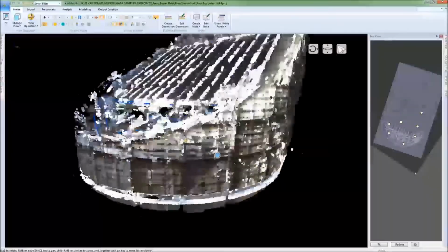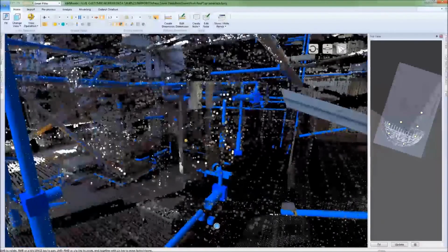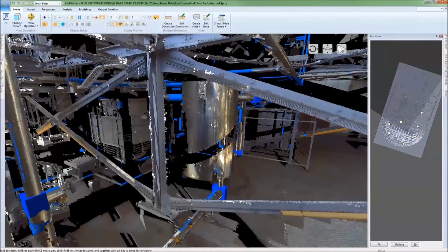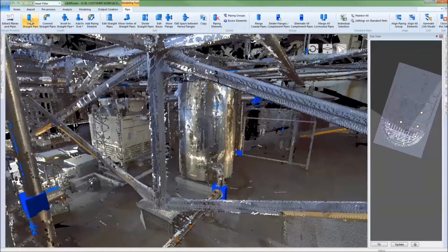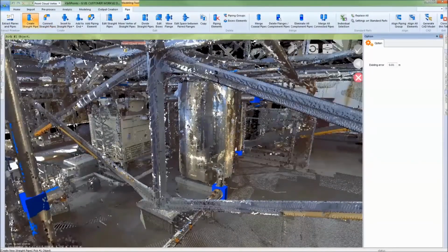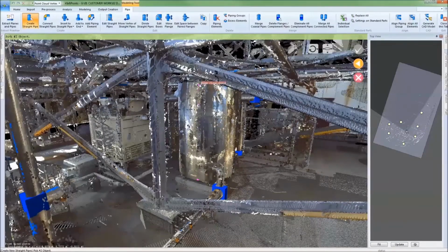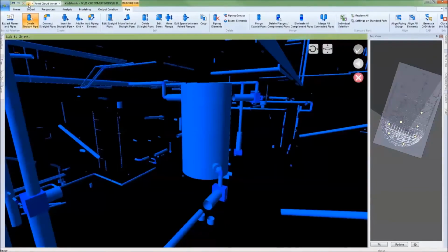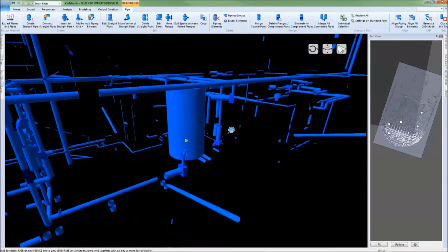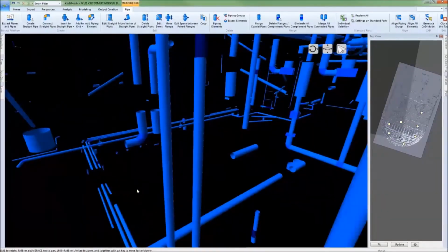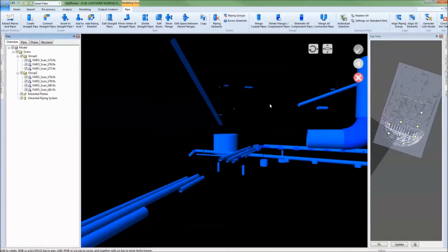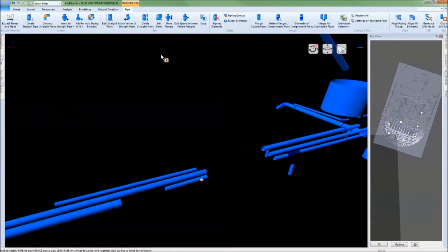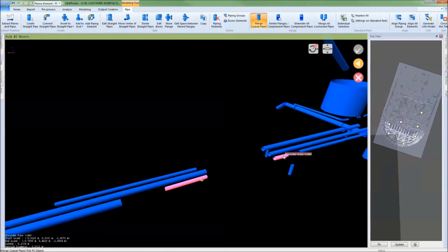Thank you, Danielle. What is great about the pipe modeling tool within InfiPoints is its versatility without the need to return to a CAD system for initial modeling. For example, InfiPoints allows for the creation of pipes based on the point cloud that may not have been automatically recognized just by selecting 2 points. From there, pipes that were automatically extracted in independent segments can simply be merged together by selecting 2 or more cylinders that are of similar diameters and lie on the same axis.